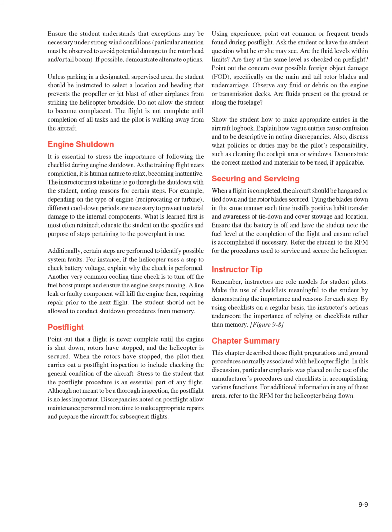Show the student how to make appropriate entries in the aircraft logbook. Explain how vague entries cause confusion and to be descriptive in noting discrepancies. Also, discuss what policies or duties may be the pilot's responsibility, such as cleaning the cockpit area or windows. Demonstrate the correct method and materials to be used, if applicable.